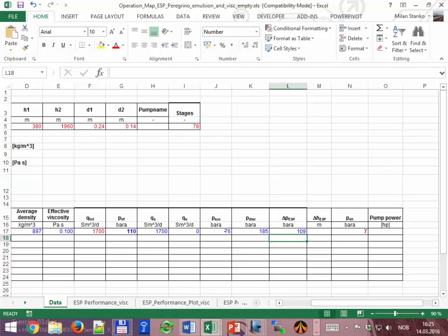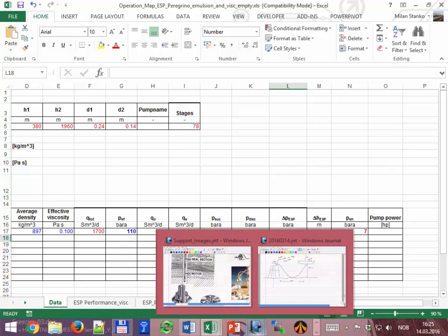Now, so far, what do I have to check to see if that operational condition is feasible or not? What's the only thing that I have told you? How they want to operate: that the pressure at the suction of the pump has to be greater than 30 bar, or 5% above 30. So is that fulfilling the criteria so far? Looks like it, okay. How much is 1.05 times 30?